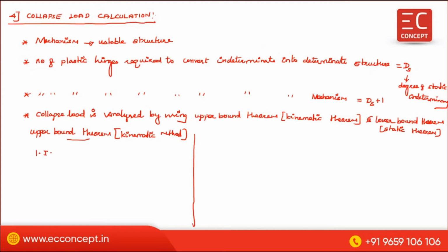It satisfies the equilibrium condition and mechanism condition. And the second one, the load which is calculated is greater than or equal to the collapse load. These two points are the characteristics you have to keep in your mind.